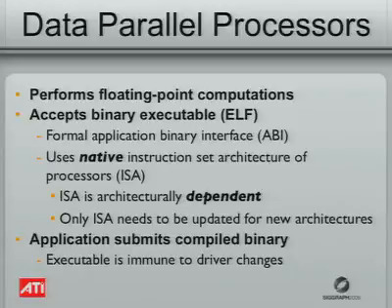But another major thing that we've added here is we've come up with a formal application binary interface. And in this sense, we've used the standard ELF format, which is one that's been adopted by many Unix operating systems, including Linux. It's basically just a very structured format for specifying a binary executable. However, in the text section, which contains the actual instructions, we're using the native instruction set architecture of the processors. So just like you would code to the x86 ISA, you can code to the x1K ISA.